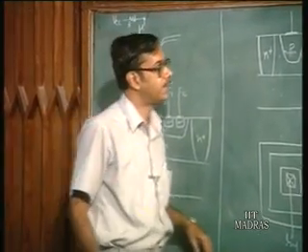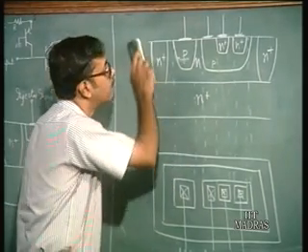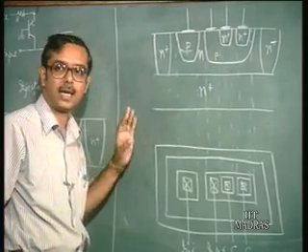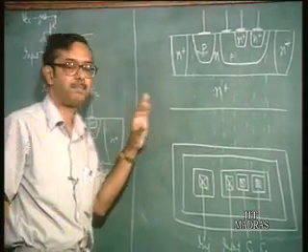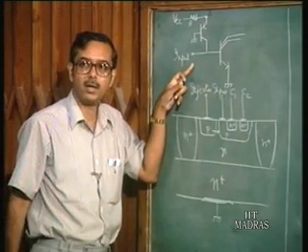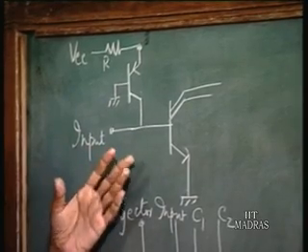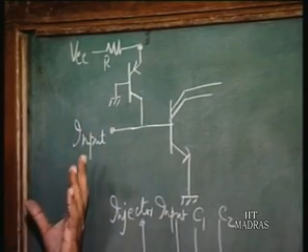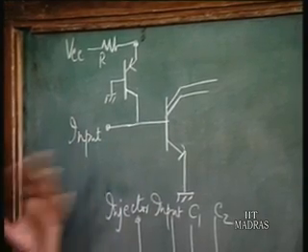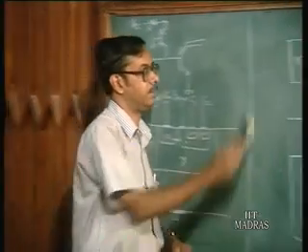Now with that we move on to more general circuits. We have now seen an I squared L cell, that is an NPN and PNP combination. Now of course our interest would be to see how you can make, for example, NOR gates or NAND gates, because that is going to act as the basic structure around which you make more complicated circuits. So that is the next step.